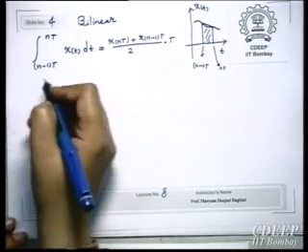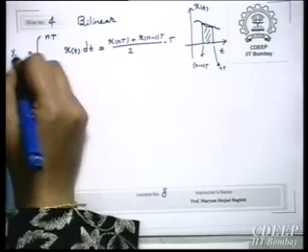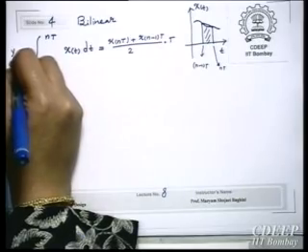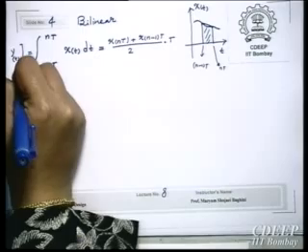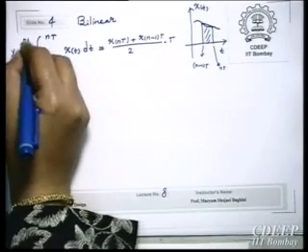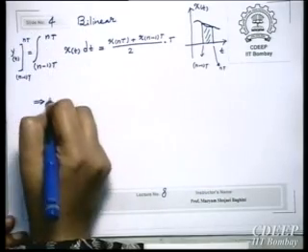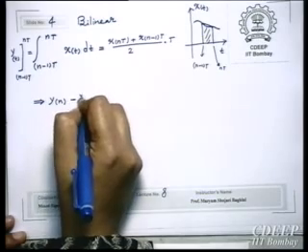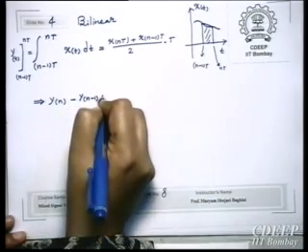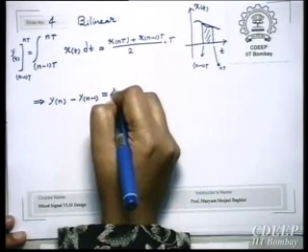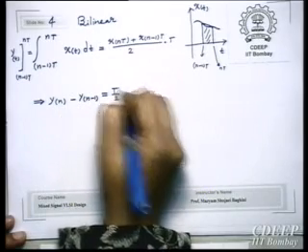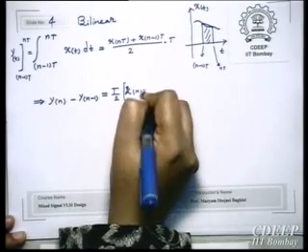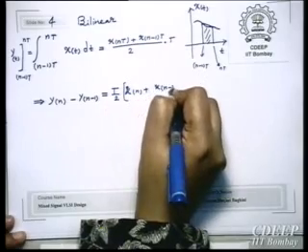And this is, for example, if I consider this y(t) from (n minus 1)T to nT. I write it in the discrete domain, therefore I just replace nT with n. Therefore y(n) minus y(n minus 1) is equal to T upon 2 times x(n) plus x(n minus 1).